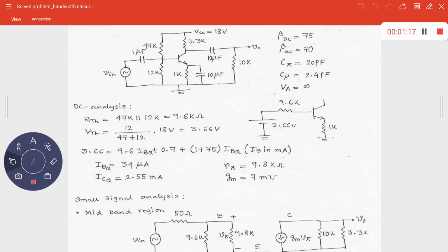Hopefully you can remember that the low frequency response is basically governed by the external capacitors like the coupling and bypass capacitors, right? And the high frequency operation, in the range of a few hundred kilohertz or beyond, in the range of megahertz, is governed by the internal capacitors. So whenever you observe the low frequency operation, the entire circuit behaves like a high pass filter. On the other hand, whenever you observe the high frequency response, the circuit behaves like a low pass filter, right?